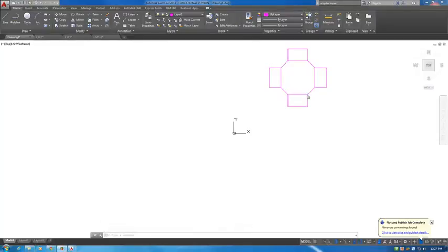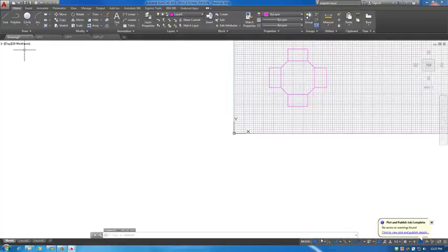Okay, so before I tried to type in a 0, 0 to move this object over to our origin. Remember, that didn't work because it's relative coordinate based. So if we specify 0, 0, it did not move anywhere because we're saying move 0 in the x direction and 0 in the y direction. Okay, so a quick way to fix this, to get this object onto the origin, is turn your grid on. So let's turn our grid on, and then we turn on grid snap. So what that is, it'll allow me to snap to certain parts of the grid.